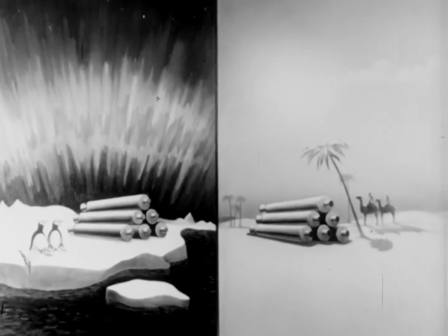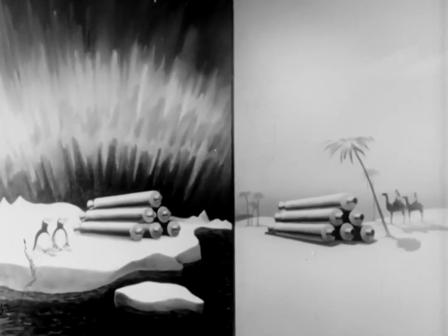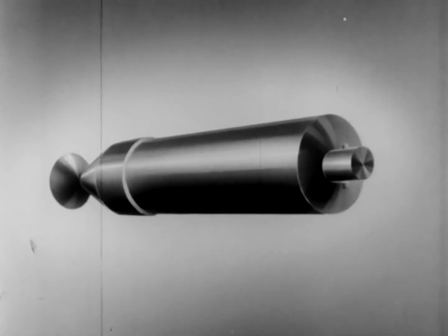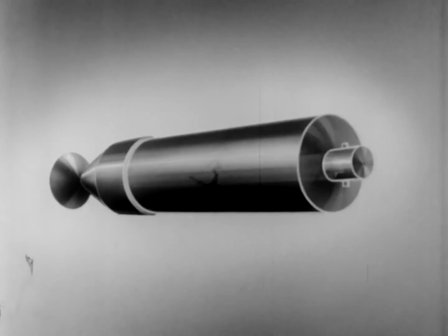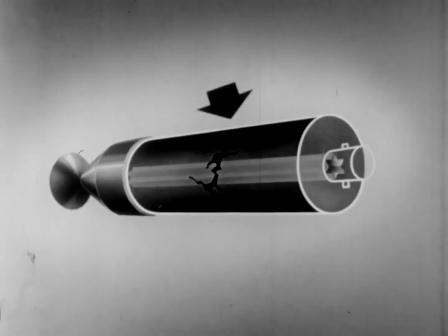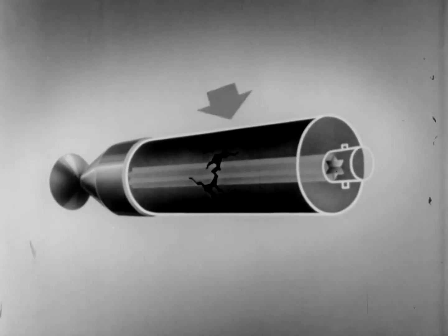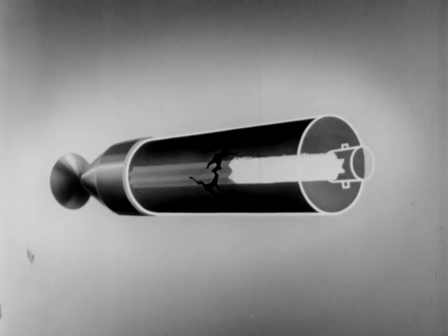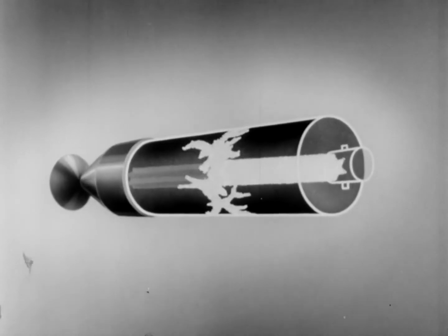However, there is one exception. Propellant grains become brittle in extreme cold and can be fractured if handled carelessly. The danger is that since the propellants are inside the combustion chamber, such a fracture would not be discovered. If this were to happen, when combustion reached the fracture, too large a burning area would be presented, suddenly increasing pressures beyond design limits, and the rocket would blow out.